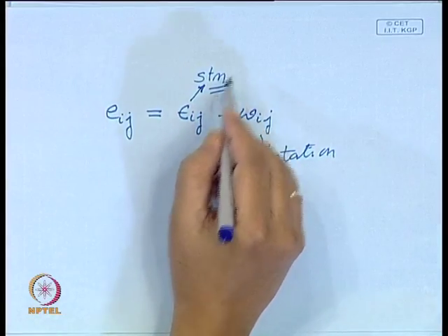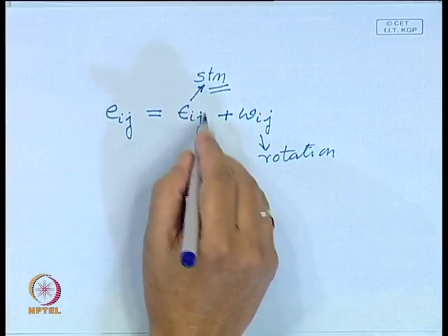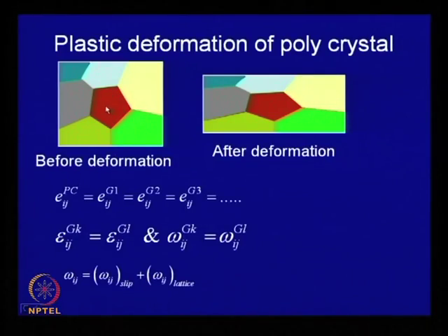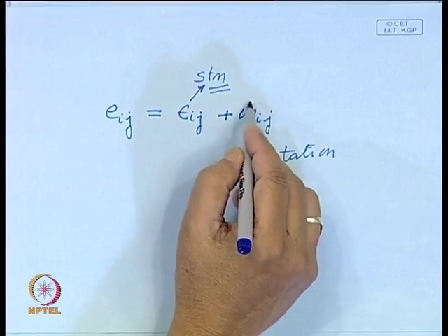So, to change the shape, this is most important, and to get any arbitrary change in shape, this particular grain will pick up one set of slip system, which gives you that identical, same strain as this. In reality, what it shows is that for each grain these strain matrices should be the same. Say, grain K and grain L, they should be exactly the same. Now, if these are the same, then this also should be the same for each grain.